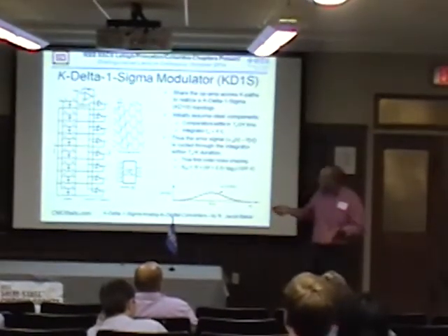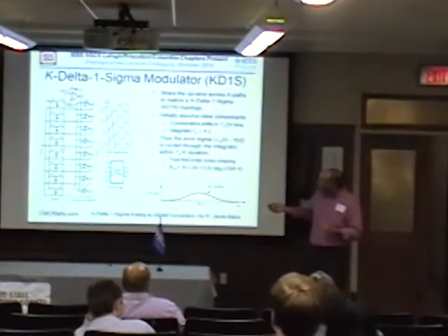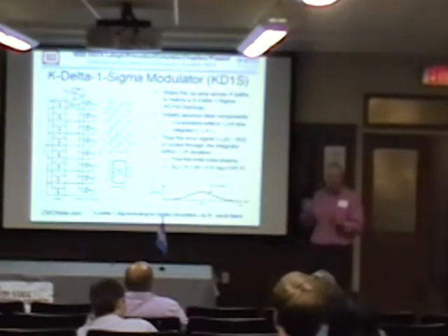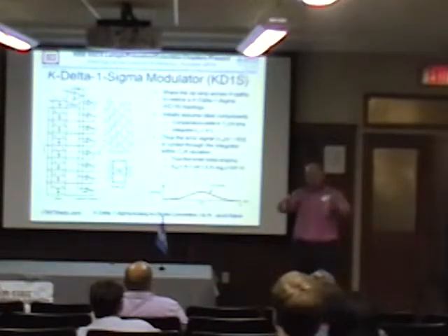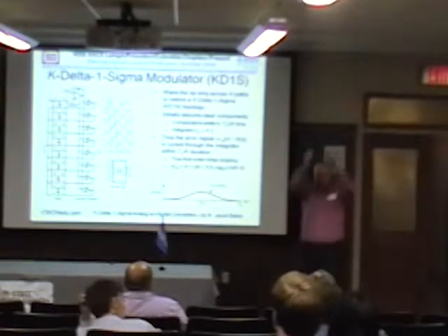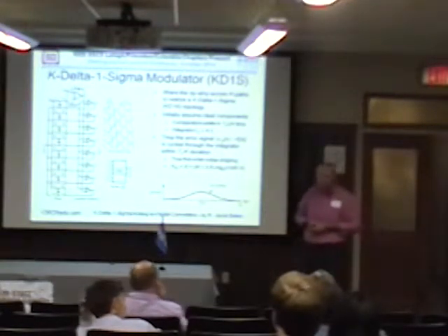The benefit here is that if you have mismatch between the capacitors and you have 8 paths, and the mismatch is truly random and not due to a linear variation, then the variance of the mismatch is reduced by the number of paths you average, and so the matching is more tolerant as well. Does that make sense? If you look at the distribution, you average K different capacitors, it squishes the distribution, so you have effectively less mismatch in there.